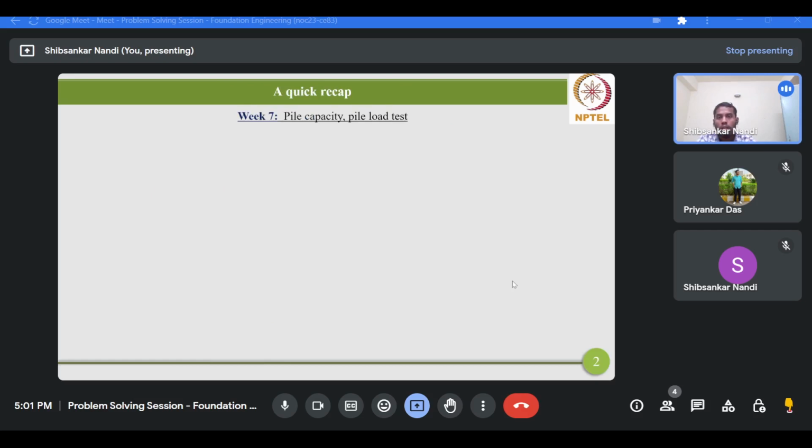We have seen the use of the static pile formula, and under this heading, the application of Tomlinson's method, specifically for the calculation of pile load carrying capacity in purely granular soil deposit, and obviously under compression. Okay, so